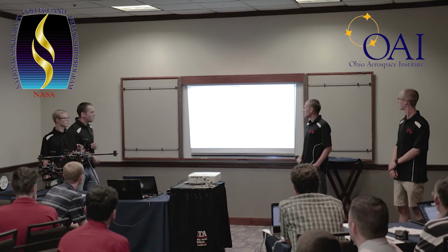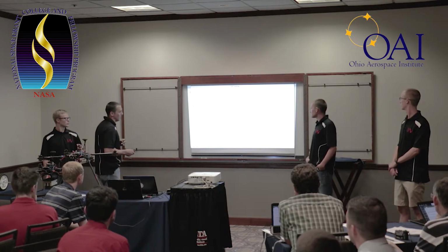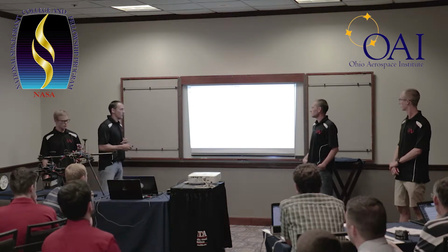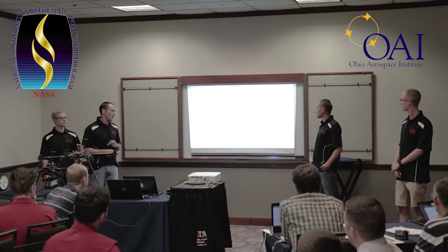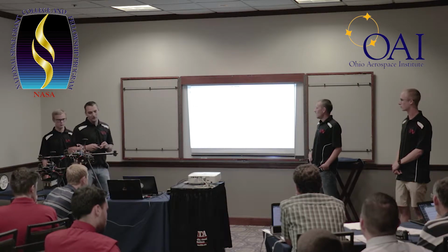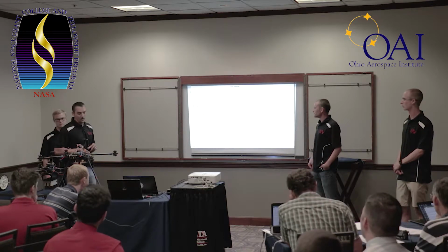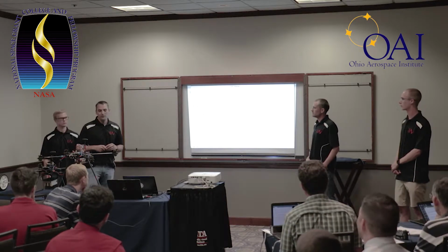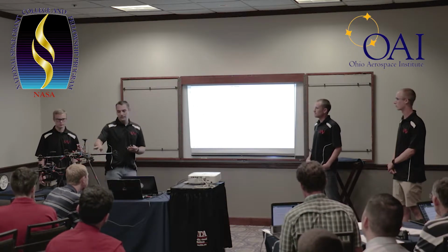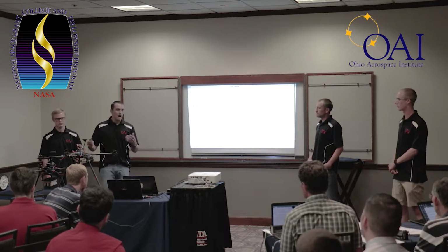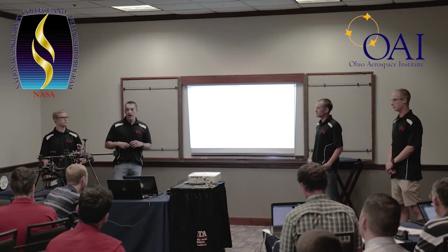Some of the specifications based on this platform itself, we just kind of list through some of the pieces. It was all built out of 3.3 millimeter carbon plate. It used 6000 series aluminum mounts and standards. Everything on here was actually built off the shelf. So motor mounts, arm mounts, everything you could buy. What we built was the plates.